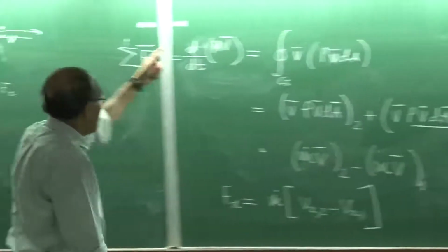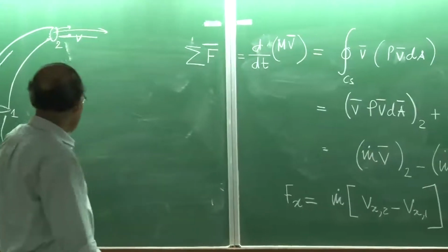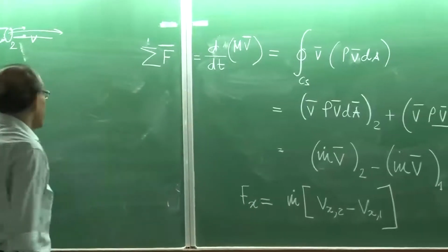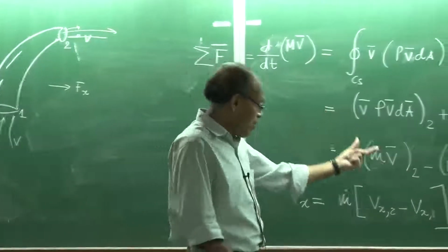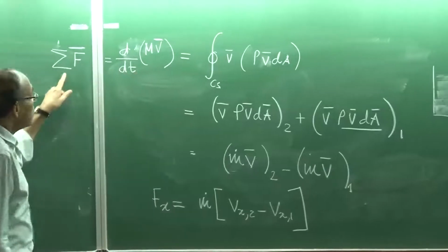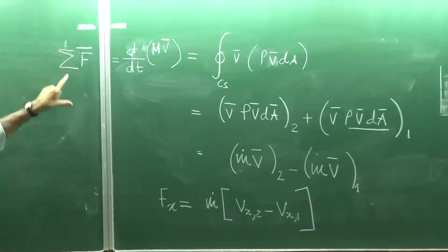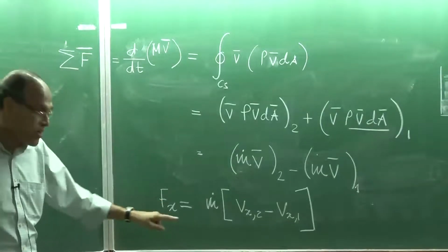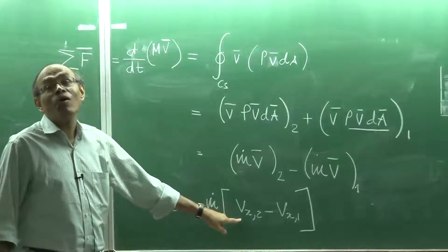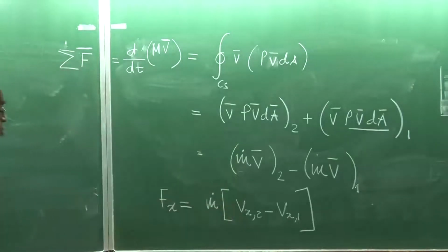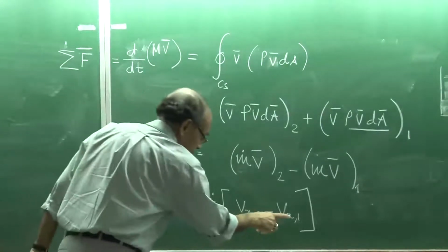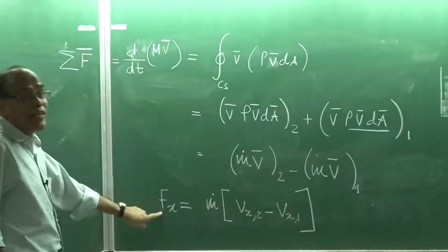So, we can perform a momentum balance by using the fundamental expression which I have written earlier in terms of capital N. In that framework, we can substitute everything and find the momentum conservation balance. And then we can split the forces along 3 different directions and write Fx, Fy, Fz also, had I been given the y and z components of the flow. So, I need the x component of the motion at the outlet, and I need the x component of the motion at the inlet, in order to find out what the force is.